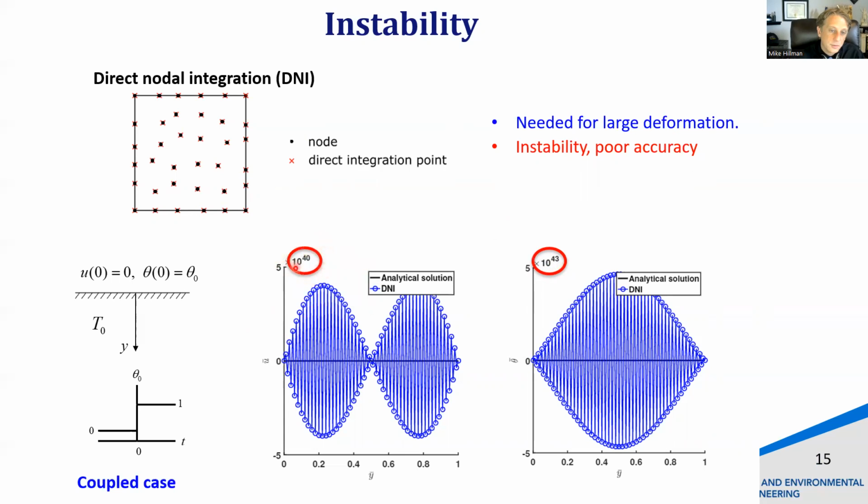absolutely unstable in time. Well, the instability in space is just growing and growing in time, I should say. And this is way worse than for pure solid problems. So this is pretty interesting here. Usually the instabilities, like the ones I showed for the Poisson equation, are on the order of the solution themselves. This is 40 orders of magnitude larger than the solution itself. So this is just going to give you absolutely unacceptable results, and you'll definitely have to do something in this coupled problem. So this is something that's pretty interesting that we found out in this research.